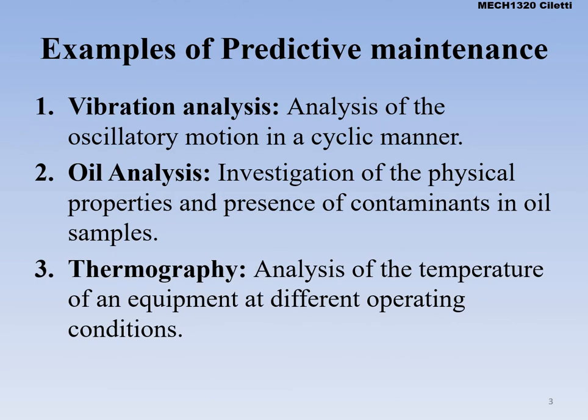If we take a look in depth at more examples, there's vibration analysis. We have a motor, and we can predict that this motor is shaking way more than it normally should. What's wrong? What's off center? That's where I talked about the wash machine a little bit before. You had too many towels on one side, so it's spinning and doesn't sound good. But we can do analysis, and there are different sensors that can tell us if the rotating motion is off kilter.